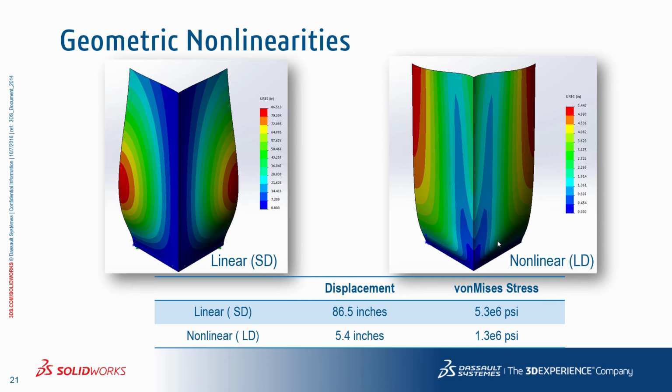The results clearly show a huge difference between the displacements and stresses for both scenarios. Note that the predicted deformation of the final shape is vastly different as well. So the question is, which is correct? When the difference is significant, as is in this particular case, the large displacement case should be considered more accurate as it accounts for the correct nonlinear behavior.